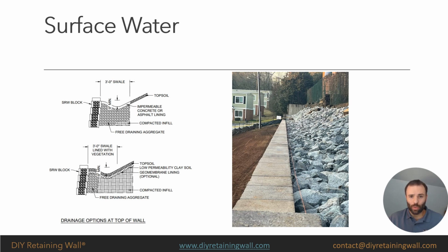Another thing to consider with slopes is avoiding runways for water to sheet flow towards your wall. This can be accomplished by using landscaping, or like the picture here, large rocks called riprap, to slow down that water and allow it time to naturally soak into the soil.